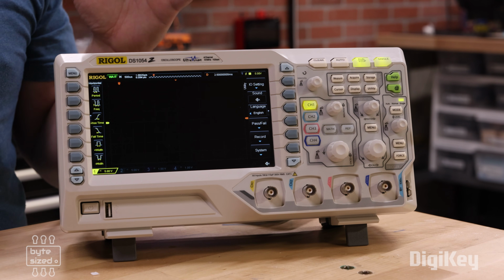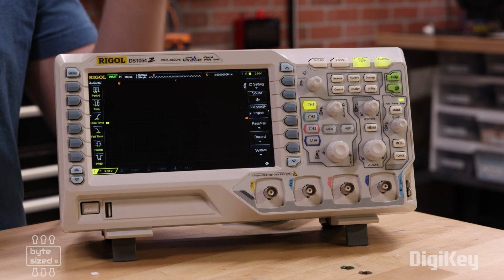In short, having more oscilloscope channels lets you measure more signals at once. A higher bandwidth lets you measure higher frequencies, and a higher sampling rate lets you digitize those signals a lot more clearly. If you're looking to get your first oscilloscope, you don't need to go crazy on those features. Quite honestly, a 2-channel, 50 megahertz scope with a 1 gigasample per second sampling rate is more than enough. There are a lot of great beginner scopes on the market that fall within that range.